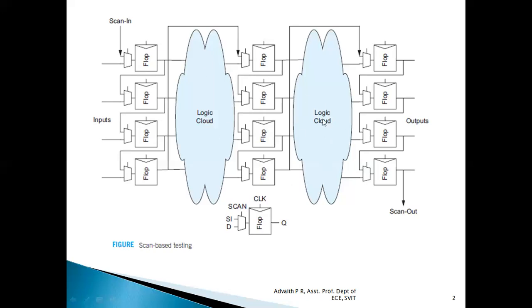This figure is nothing but modern scan-based testing of registers. Here we have considered a D flip-flop. The scan register is a D flip-flop preceded by a multiplexer.